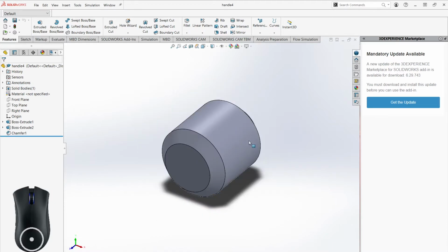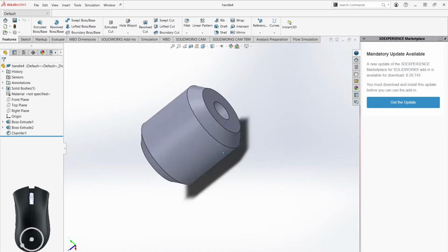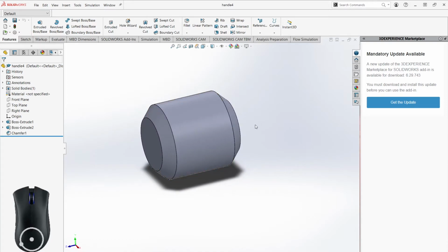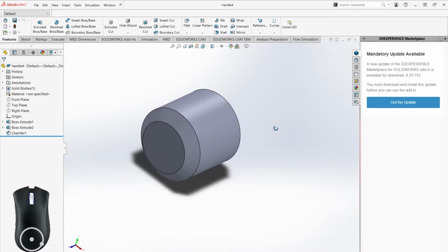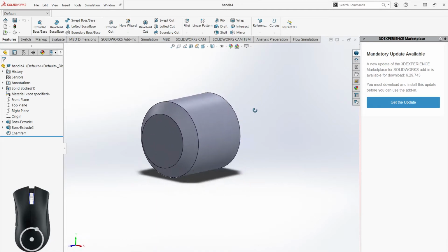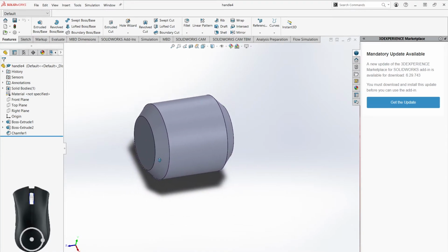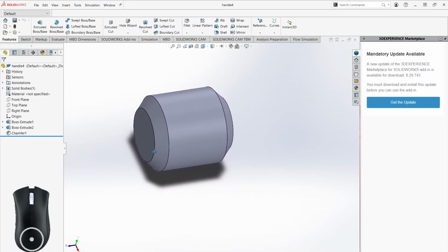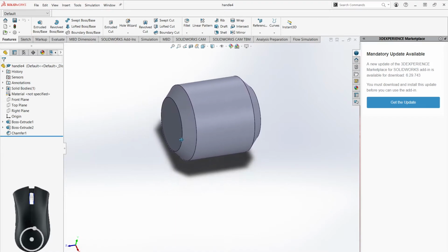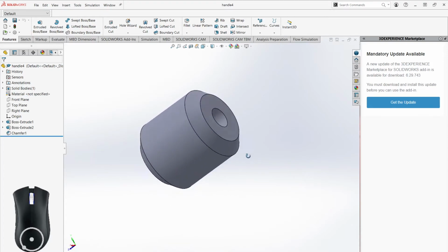And you may be wondering how I've been able to pan around or rotate like this. I'm doing that by holding down the middle mouse button to rotate. This is me holding down the middle mouse button. It turns my cursor into the rotate icon, and I'm rotating around. And if I hold down Control and the middle mouse button, that's when I get to pan. The cursor becomes a little moving icon, so I can move it around linearly. And this would be like rotationally.